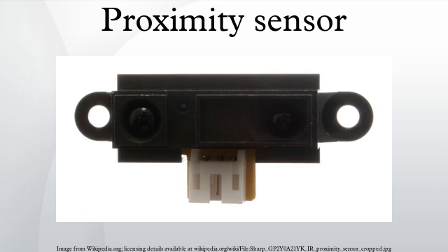The object being sensed is often referred to as the proximity sensor's target. Different proximity sensor targets demand different sensors. For example, a capacitive or photoelectric sensor might be suitable for a plastic target. An inductive proximity sensor always requires a metal target.